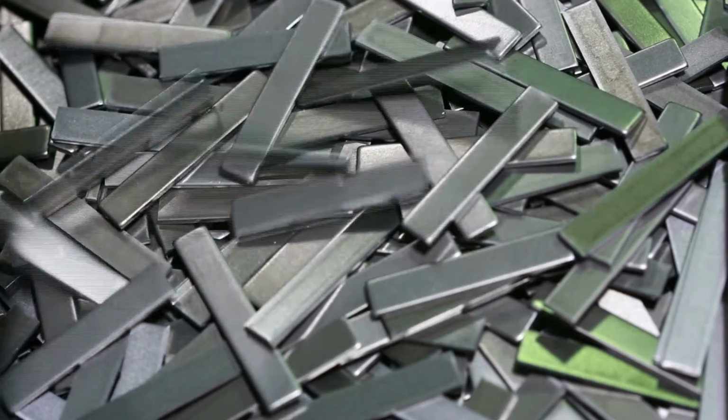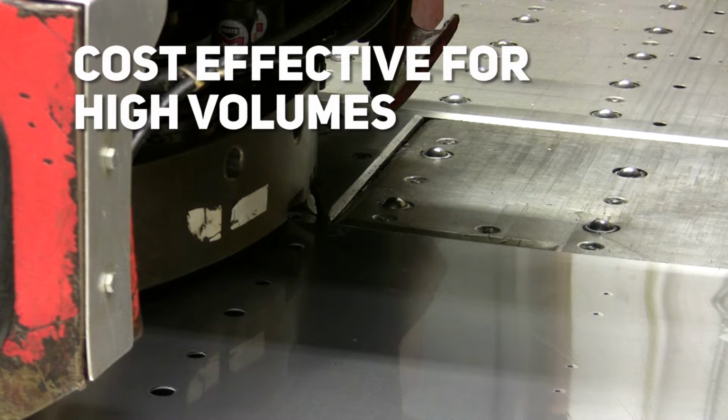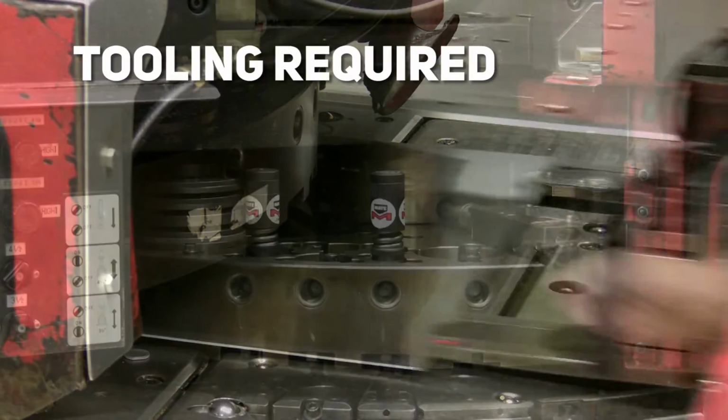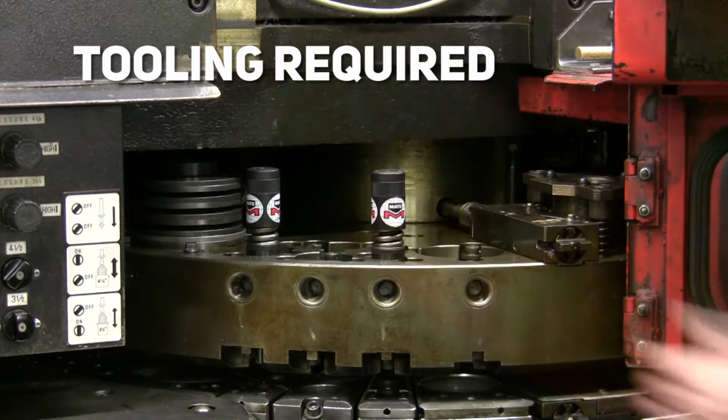Punching is quick and the most cost-effective process of making holes of varying shapes and sizes in strip or sheet metal for medium to high production volumes. However, if existing punches do not fit or meet job requirements, custom tooling is required, which can be costly.